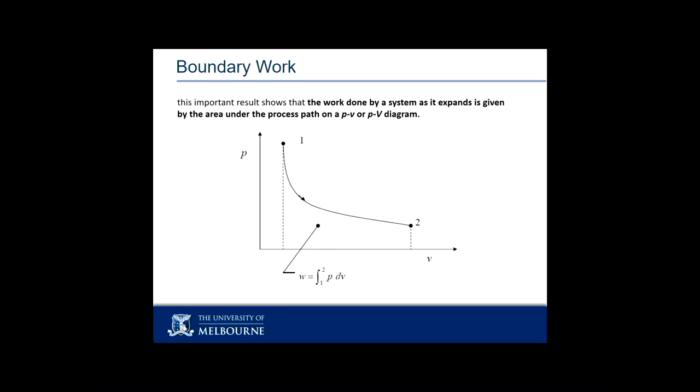If I went back again to some other state, the difference between the areas of the two graphs would give me the change in work, would give me the change in the energy of the system. Then if I had some thermo, I could tell you what the final temperature was. Because if I knew the state, if I have two properties, it's a PV diagram. I have two independent properties, and as soon as I've got a dot on that graph, I have all the other properties of the system. So by one tiny little mathematical change on this force times area times dx, now I have an expression for work that is suddenly useful in a thermodynamic sense.